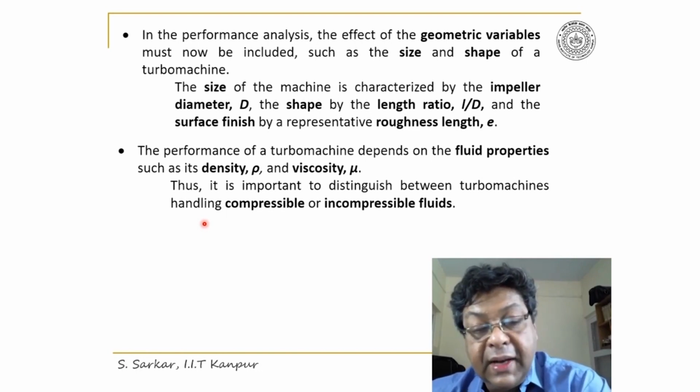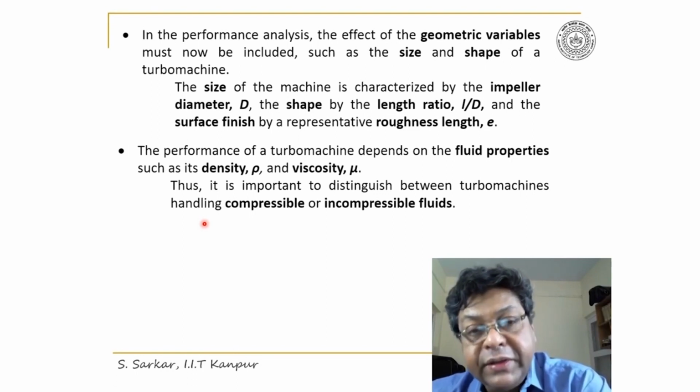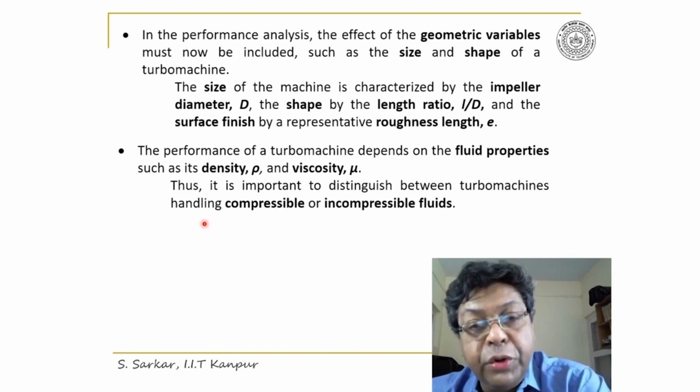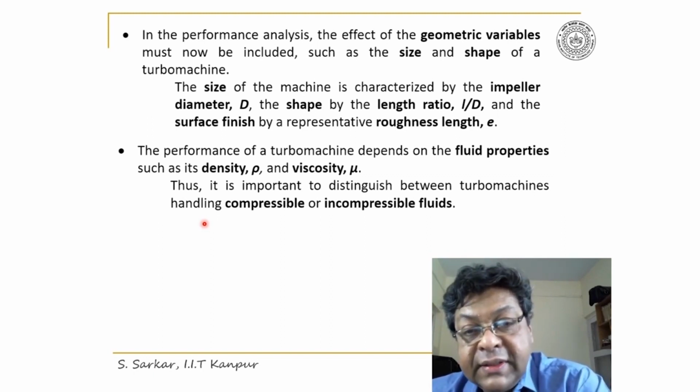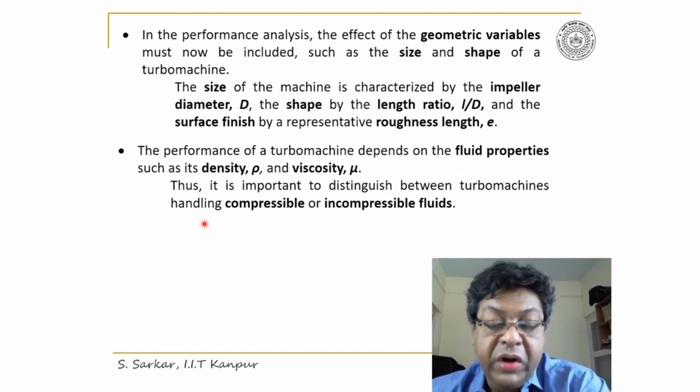Thus, to summarize, for a similarity analysis, we need to consider geometric variables, fluid properties, and the fluid media, whether it is compressible or incompressible.